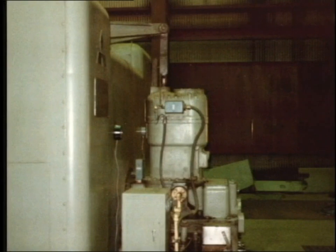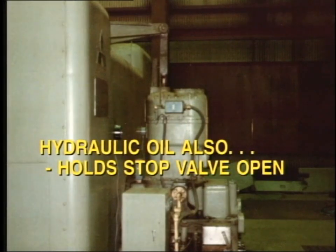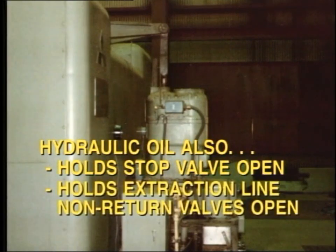Well, the high-pressure oil is used as the medium for operating the turbine control system. For example, the servo mechanism, which provides the force to adjust the turbine admission valves, is motivated by hydraulic oil, hence the high pressure needed. Hydraulic oil is also used to hold open the turbine stop valve during operation and hold open the extraction line non-return valves during normal operation.